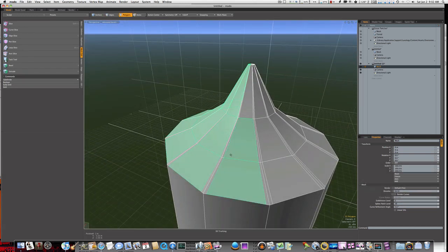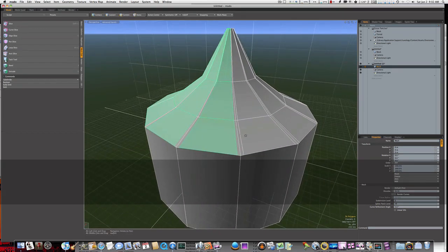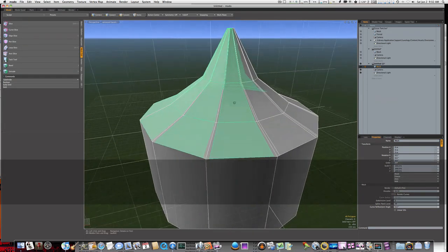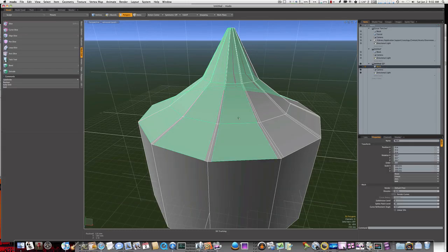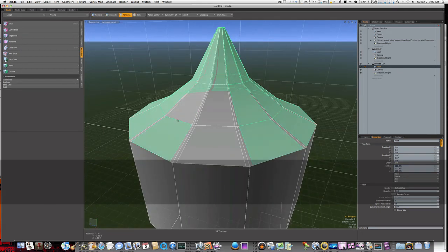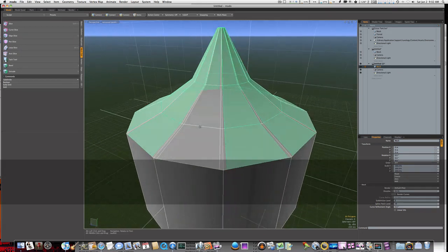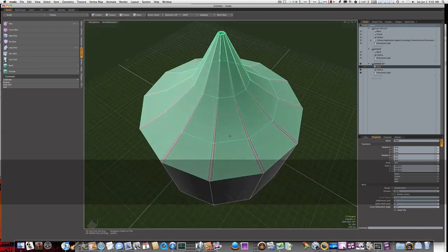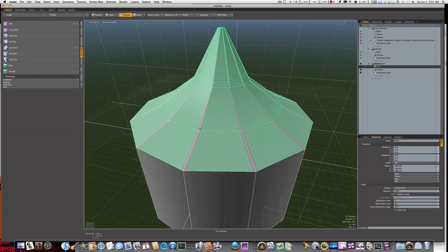all of my geometry, or I should say the rows of geometry, skipping the creases. So just go around, select 2 in the direction you want it to run, and hit the L key and it will finish your loop. Select 2, L, and boom. Now as you can see, I have all of them selected except the creases.